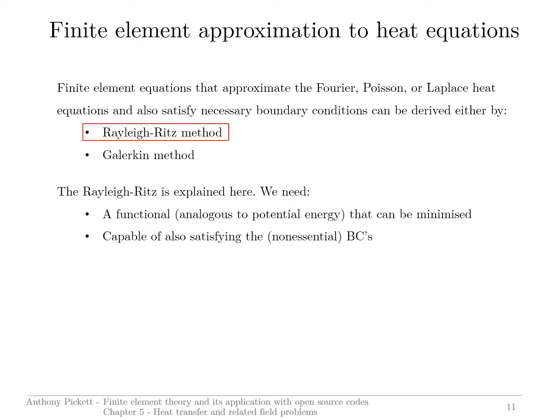Again, just to remind you, the different types of governing differential equations are usually either the Fourier, the Poisson, or the Laplace representation. And each of these governing differential equations has to satisfy necessary boundary conditions. The finite element equations for this can be derived by either the Rayleigh-Ritz method or the Galerkin method.